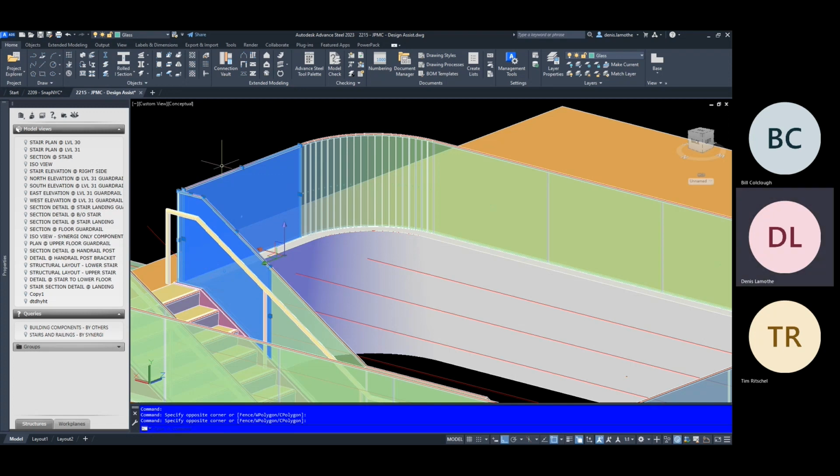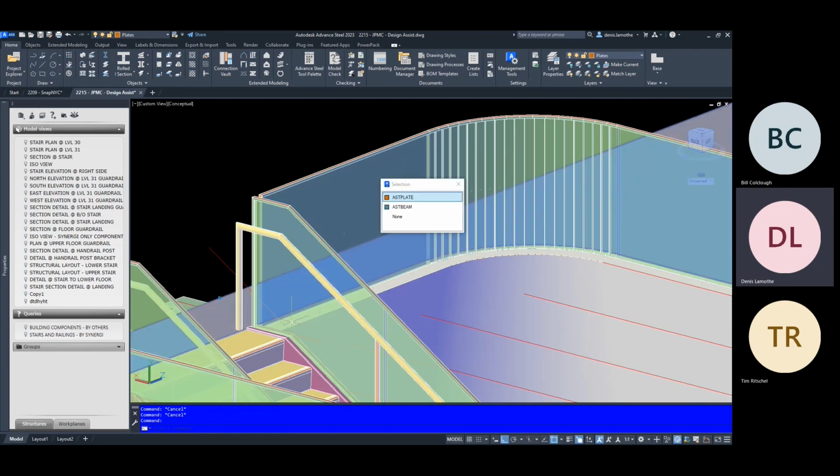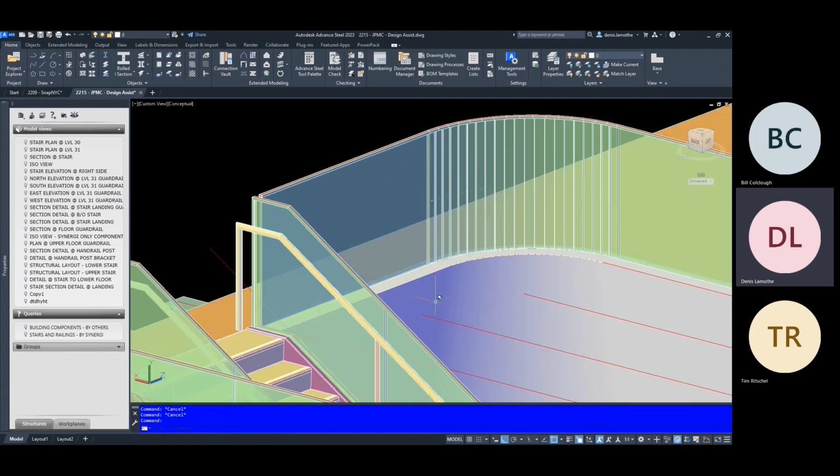If we had initially installed these railings at 3'6", but there's more material on the floor, then we're going to end up with less than 3'6" overall height to finish floor. So that 1/2 inch allows us a little bit of wiggle room for any condition that might pop up on the job site where the floor might have crept up. Maybe we did only a partial survey and there's a spot further down the railing where the floor height went up by at most half an inch.